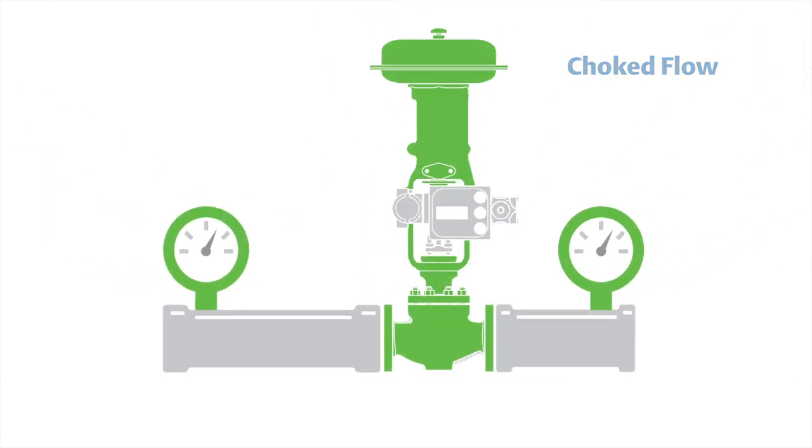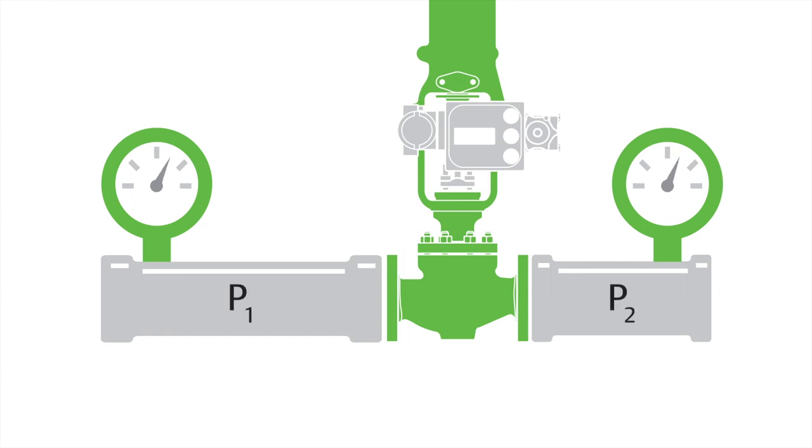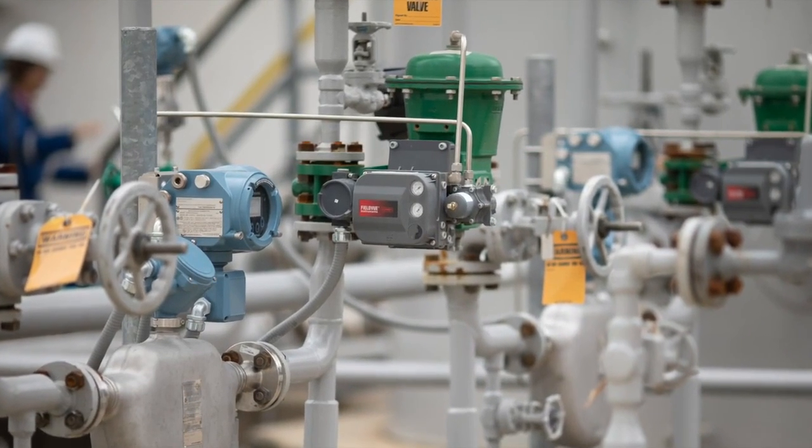Choked flow just lets you know that some of the actual pressure drop going from P1 to P2, inlet pressure to downstream pressure, will not be used to push the flowing media through that control valve. As a result, the potential for bad things to happen can exist, if the wrong control valve style and trim type are selected. This is why so many styles of control valve bodies and trim types have been developed over the years.